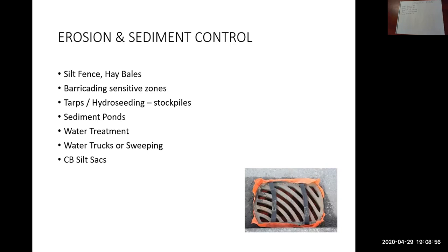Possibly you may be required to excavate sediment ponds. Those are typically shown on your drawings. You don't have to come up with things like that. You're shown how big the pond needs to be, with any pipe work that comes in and out of it. So you would do a takeoff there of how much excavation you have, how much pipe, etc.